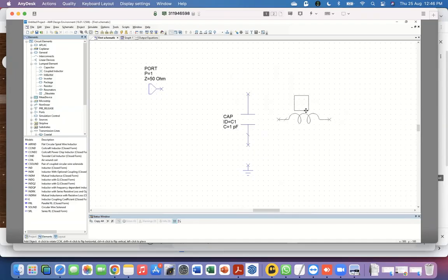And while you have not clicked anywhere, you can right click and cause it to rotate like this so that you bring it in the right orientation. So then you drop it and then you can connect this. So remember this icon changes to this wire whenever you go onto the terminal. And you have to click there. You cannot click in other random places. Okay. So that completes this circuit.